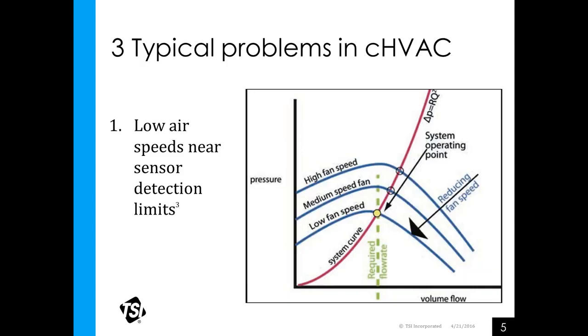Running an HVAC system costs money. One of the goals is to save money. A lot of people mistakenly think ratcheting down the volume helps save energy. It doesn't. It's almost as bad as going in your home, going through your system and closing vents, thinking you're going to be saving money and reducing money expenditures on your HVAC system.